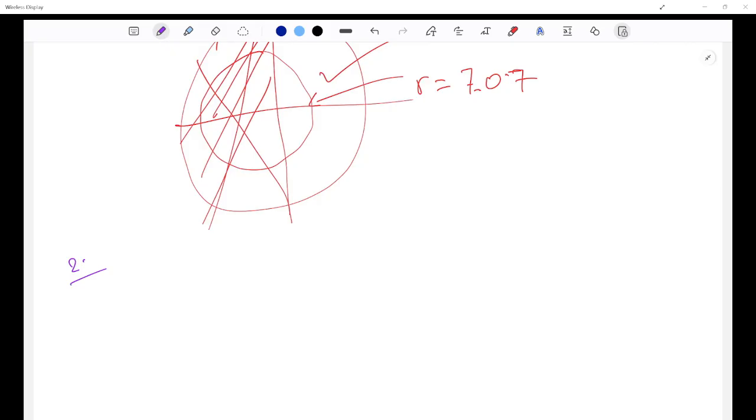It should be a systematic procedure and not saying that if both of them lie between minus pi by 2 and pi by 2, that means I can move in a circle in the right half of the plane and the complete right half of the plane is my answer. No, it is not, because you have an inner limit, and that arises because when you have a limit on the second joint as well, you have to take care of how much it can move. Okay. You can do this analytically as well, by the way.